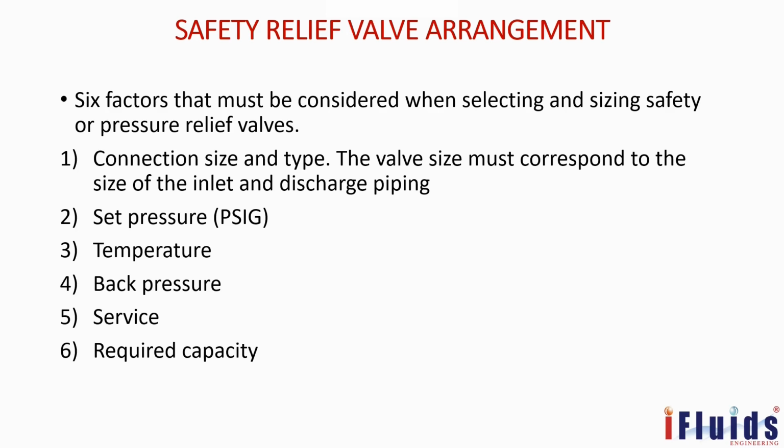The back pressure is very important when designing the PSV, because these PSVs are connected to a drain line, maybe or with a flare header. There are different types of PSVs connected to the same header from different units. So at that time, if any of the higher pressure PSVs pops up, that pressure may come back to this PSV, which is in normal position, and damage the internal parts. That's why we have to think about the back pressure of the line during the design.